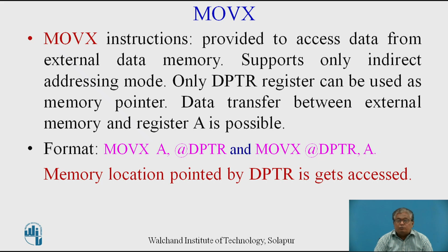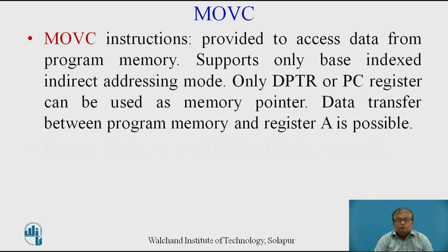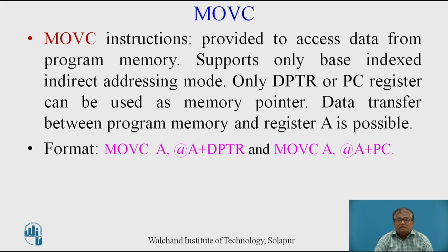Memory location pointed by DPTR gets accessed in the MOVX instruction. The MOVC instruction is to be used to access the data which is stored in the program memory.